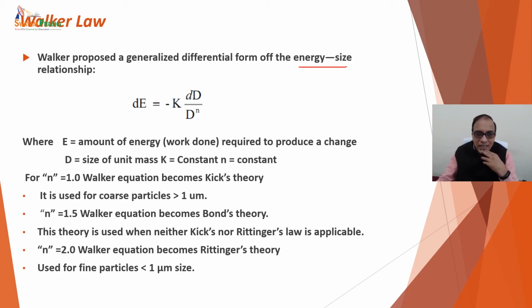He expressed it with the equation dE is equal to minus K dD upon D to the power n, where E is the amount of energy or work done required to produce a change, D is the size of unit mass, and K and small n are constants, with n being the power in the denominator. When n is equal to 1, the Walker equation becomes Kick's theory. This you should keep in your mind.